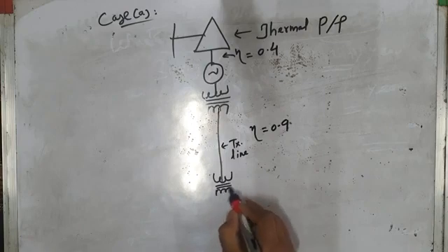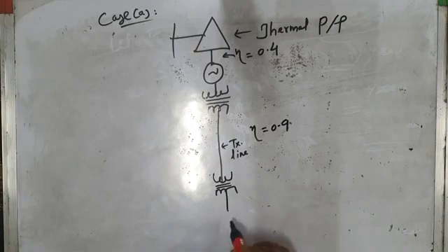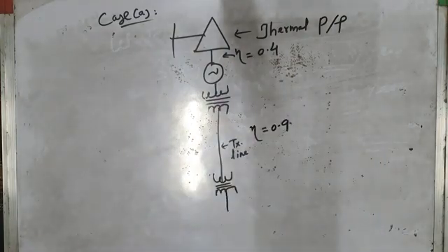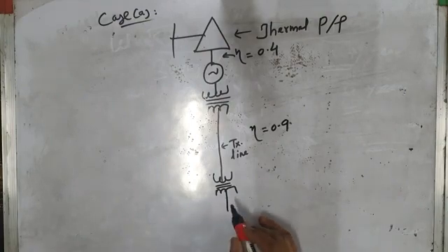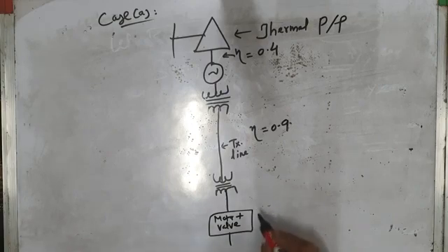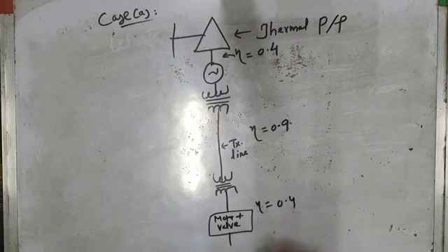Then we have distribution step-down transformer, and let us assume we use a load. Say, let us take same type of load, pump, and in the case A, we will take conventional motor-driven pump, and this is motor plus throttling valve, and then the efficiency of this motor and throttling valve is again very poor, just 40%.